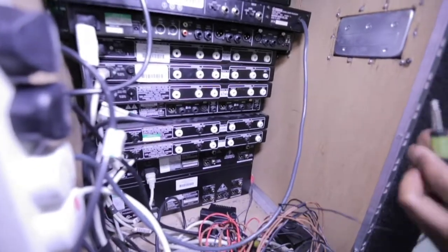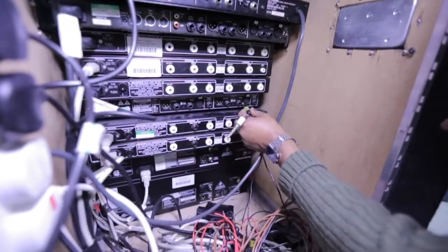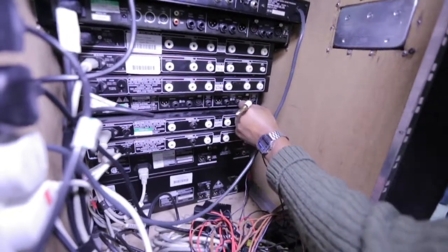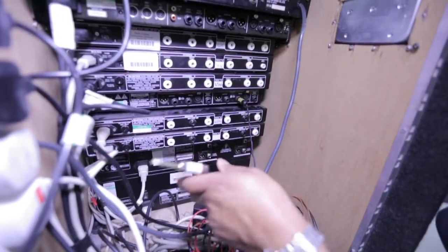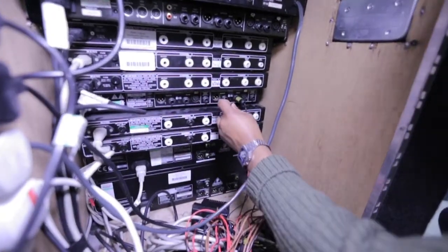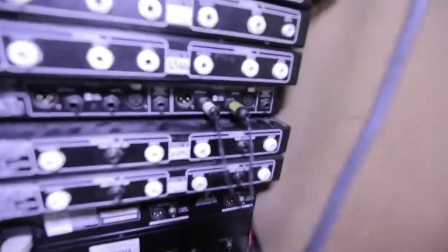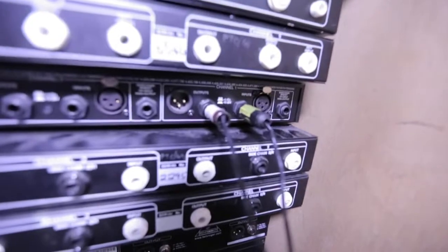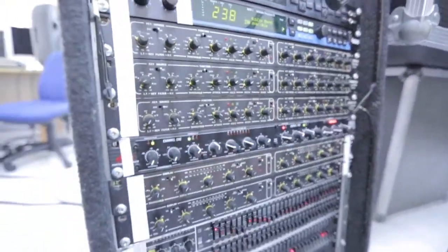Then move into the stereo output bus. On the back of the compressor, I will take the corresponding jack connector labeled 1, carrying the signal from the desk, and connect it to the channel 1 input. Then the jack connector labeled 2 will plug into the output of channel 1. This returns the compressed signal into the desk.